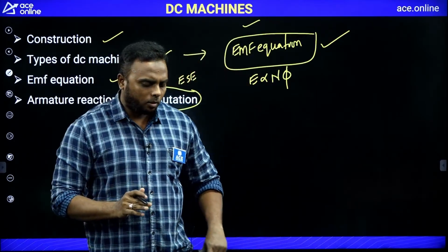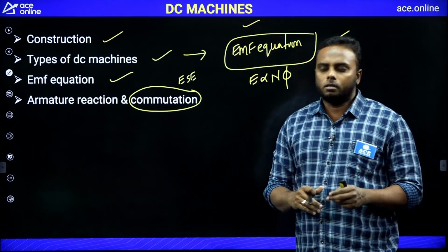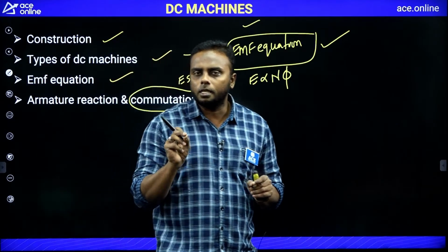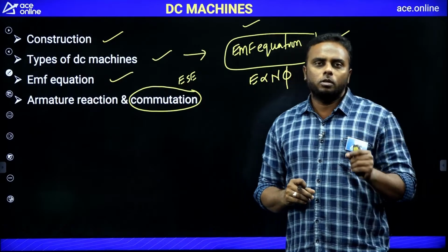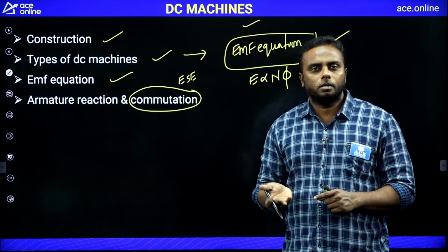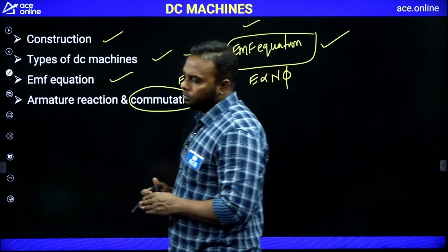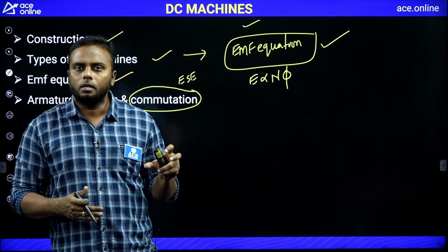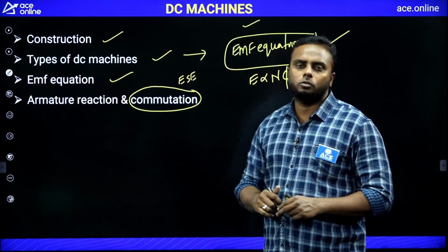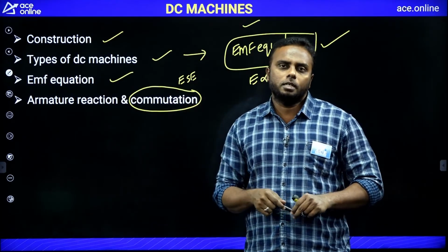Now this is mostly a theory topic. What type of questions can we expect from armature reaction? During armature reaction, at what pole tip does flux density increase in a generator? The trailing pole tip. For motors, it becomes the leading pole tip. And there are some questions on the methods to reduce the effects of armature reaction. And what happens if the brush is shifted in the generator direction.